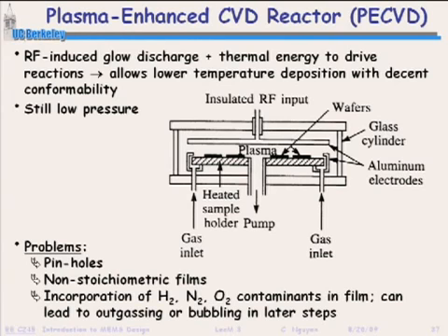Now there are ways in PECVD where you can actually control stress by changing powers as you deposit. Deposit at high power, low power, high power, low power. So you're getting different stresses that are acting against each other. But I wouldn't try that at a university. In production, maybe you can do that. But at a university, it may work once. But the next time you try it, you got to redesign the whole thing. Because the equipment in the university are just not dialed in. You got all sorts of people using the same piece of equipment. Every time you use a piece of equipment in the university, you always need to dial it in yourself.